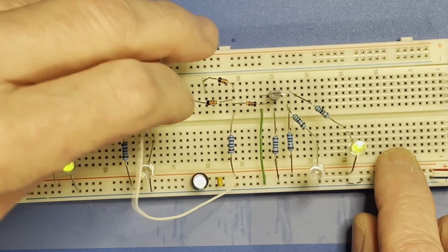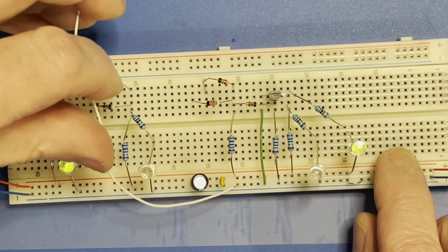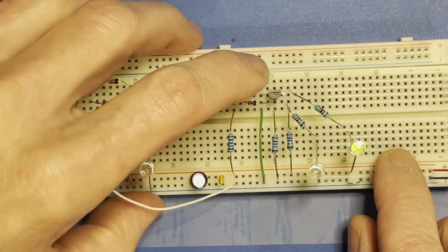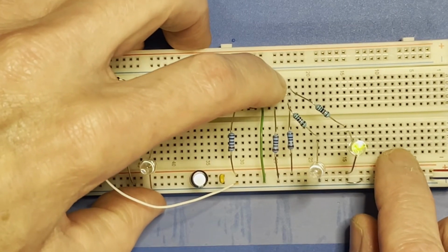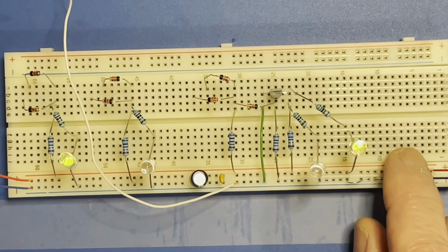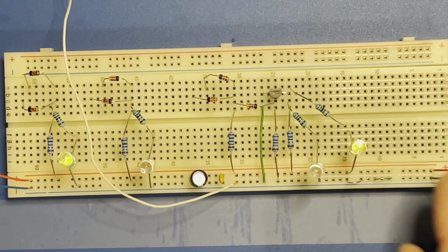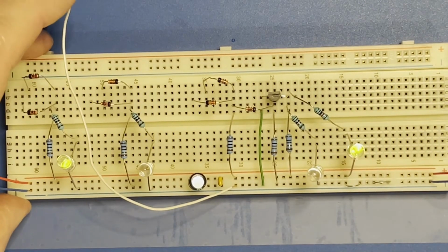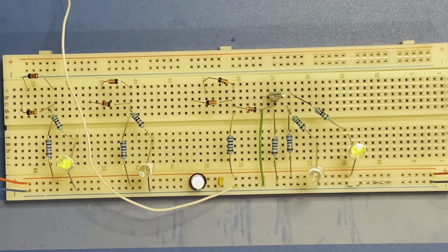This circuit will not work at anything other than very, very low frequencies, because, as I pointed out earlier, that transistor is saturating. It's turned on very hard, and the collector is being pulled down to millivolts. Now, I'm going to use an oscilloscope to demonstrate the frequency, and I'm going to screen record the oscilloscope so I can mix that in.